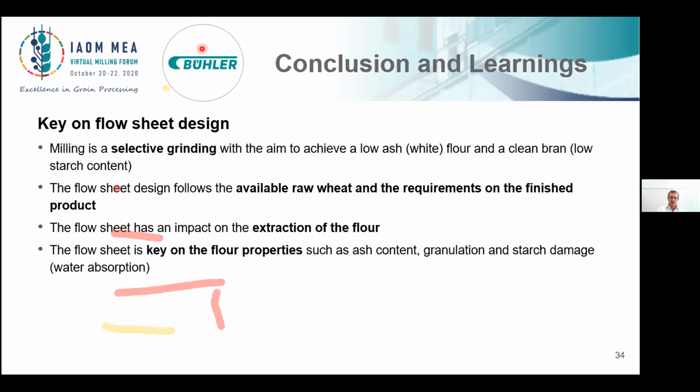So this can be done with roller mills. Now, the wheat conditioning is key for damaged starch and the rolls. We always start on the wheat. When we want to have a damaged starch, the British are experts on that. They keep conditioning time low to keep the core of the endosperm still vitreous, and they reach a higher damaged starch. But that is not always possible because you will lose some moisture.